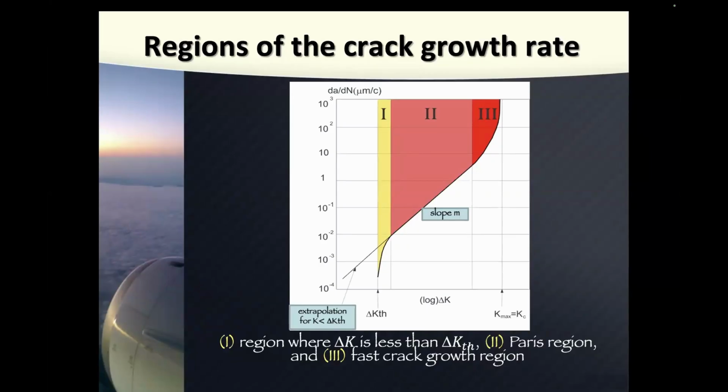Why delta K? Let me remind you that fatigue is caused by dynamic loads, and these dynamic loads are changing over time, and we can identify the maximum and minimum load. And then we talk about range of the stress. We can calculate the stress intensity factor for the maximum value and for minimum value, and then we talk about range. So we discovered that range is, in fact, the most influential when you talk about crack growth.